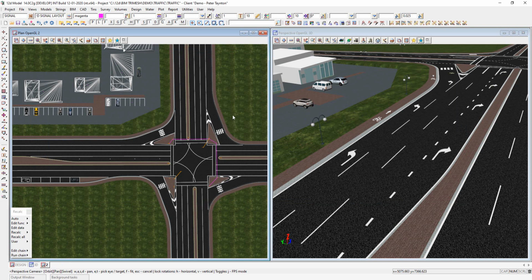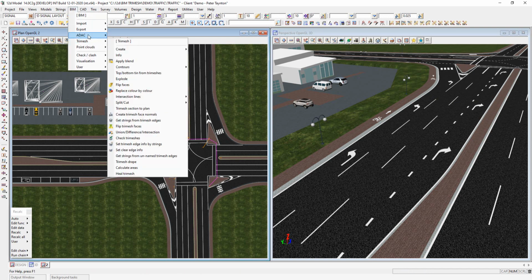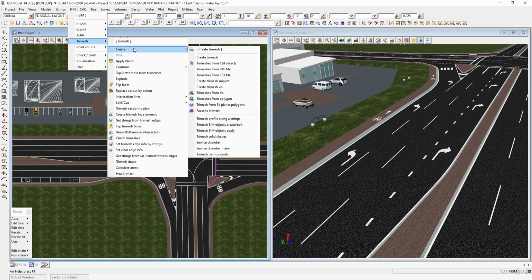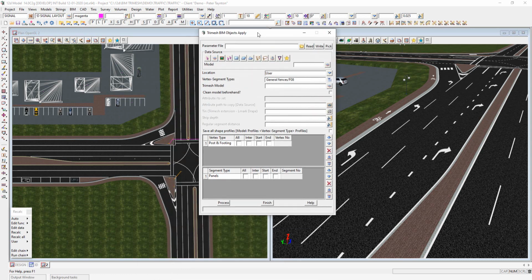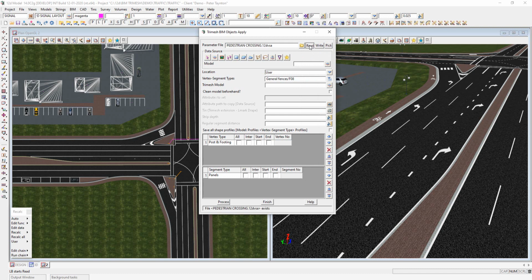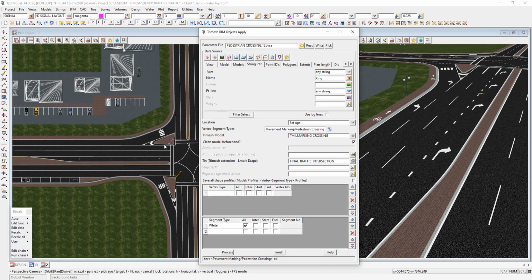For things like the chevronning and those types of things, and also the pedestrian crossings, again they're simply a style that has been created there for you. The chevronning or the crossing has been saved, so it's the same thing. You just pick a string, and from the list you grab pedestrian crossing instead of line marking or directional arrows. So same sort of process, just pick the string.